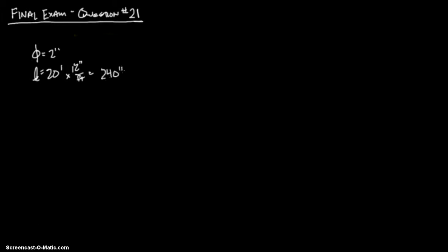240 inches. Alright. Then it says resist a tensile load of, and we know P equals, typically as how I denote tensile or compression loads, of 50,000 pounds. Alright. Says how much is elongate. Assume E equals 29 million, which is a very, very good assumption. I've never not assumed that E equals 29 million for PSI, that is, for steel. Alright, that's a good assumption to make.